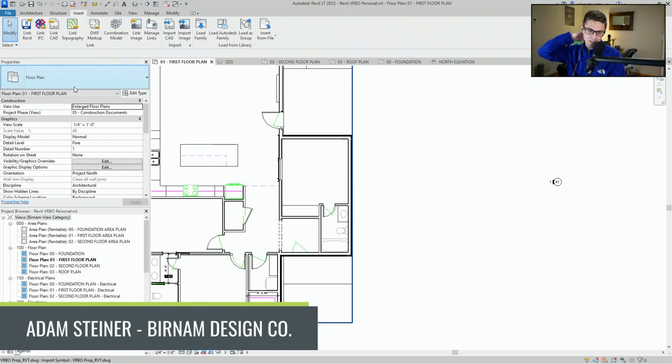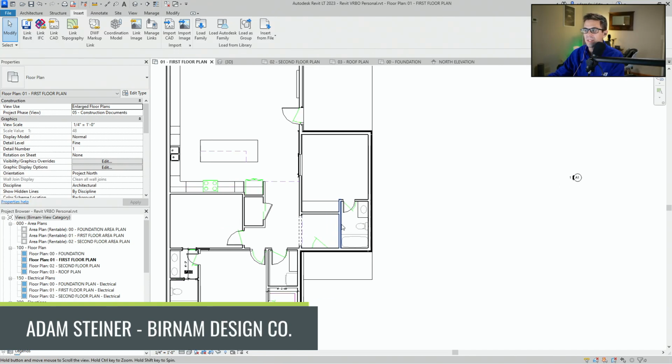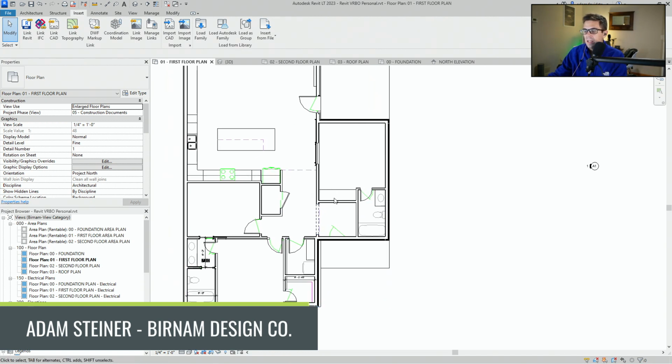Why do architects like to measure to the center of the window? I think it's because window rough openings change slightly based on selections. And if you do like edge to edge, you have to know exactly every single window while you're doing CDs, which you don't always know. And sometimes clients adjust things, and usually the CDs are done before the windows are bid out.